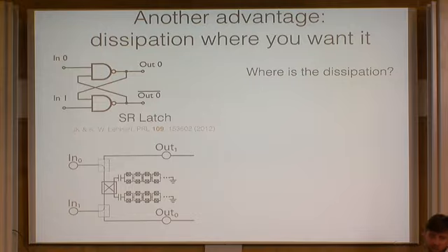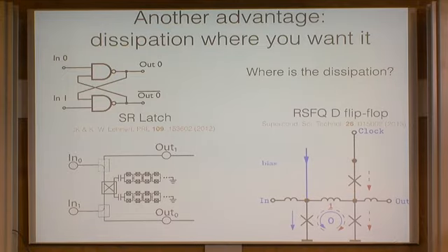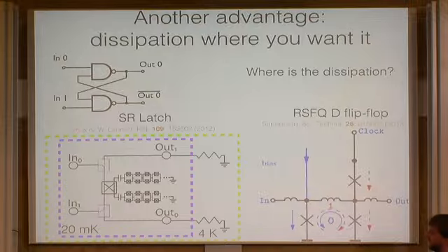But each of these things individually should have no dissipation. Digital information technology in cryogenic systems is nothing new. I think even going back to the 60s, people were at least thinking about, if not already doing, information processing using what's called rapid single flux quantum. The distinction here is where's the dissipation. In my case, the dissipation that allowed this thing to latch actually happened at a higher temperature. The output of here went to resistors that I put at the 4 Kelvin stage, the hot temperature stage, because that's where it could handle a lot of power dissipation. So that's why I put it there.